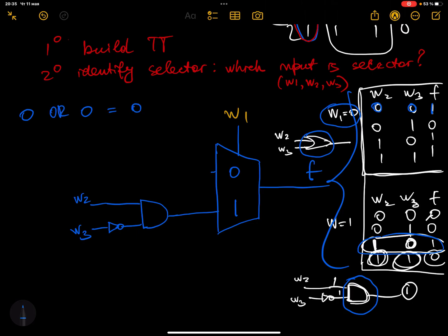But in this case you're getting 1, so one of them should be negated. Again, let's choose W3. So I'm checking our guess. My guess is that the gate is an OR gate and W3 is negated. I put the values here: this is 0 and this is 1. This is 1, but it is negated, so it becomes 0. Overall, it produces 0.